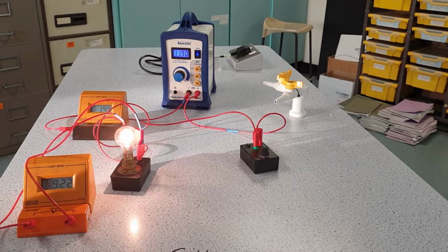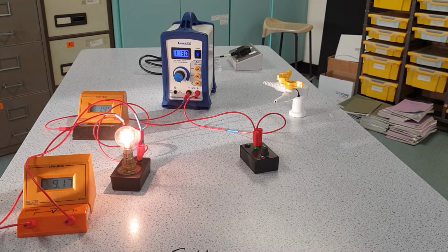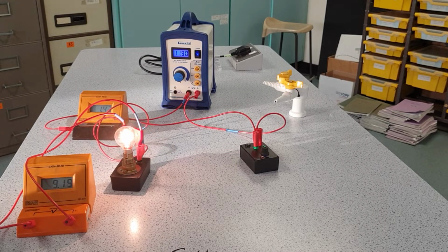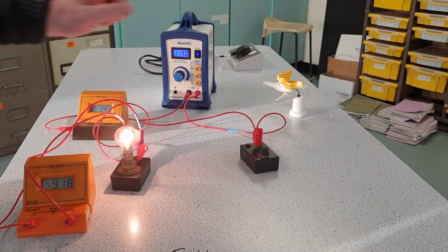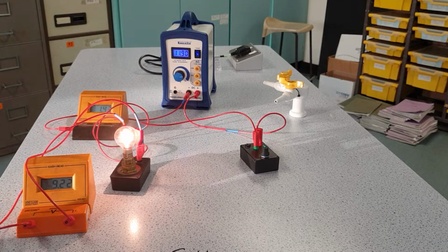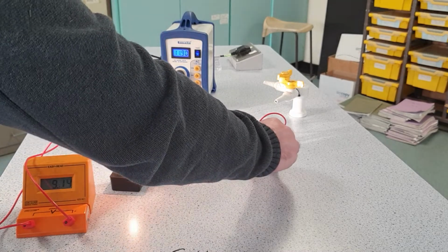So we might want to do an experiment with a light bulb where we're investigating how the resistance changes with voltage, or indeed how the current changes with voltage. And that's where this variable resistor comes in, because the variable resistor will allow us to change the voltage just across the light bulb. Now, we set up the power pack to output a constant 12 volts across the whole circuit. But by varying the resistance of the variable resistor, we can change how much voltage we get across the light bulb. So, for example, if I increase...